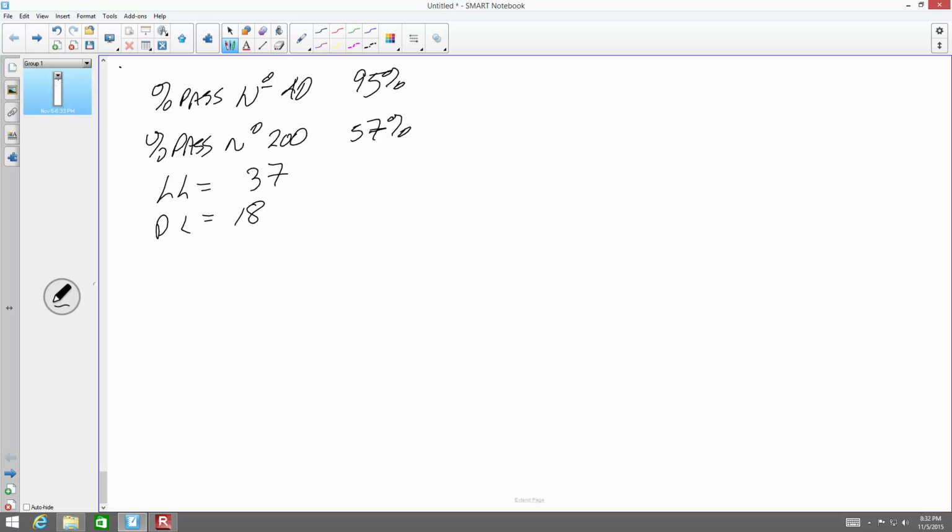A granular soil tends to densify and settle if subject to vibration and seismic shaking. When the saturated granular soil undergoes seismic vibration, it becomes subject to cyclic shear deformation, which causes an increase in pore water pressure. The result usually is a severe reduction in effective stress.